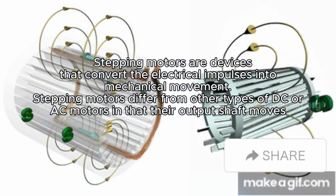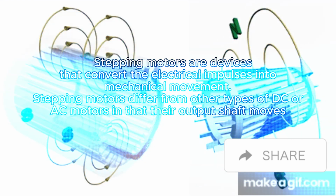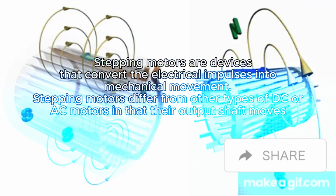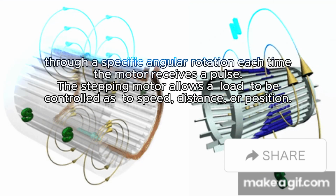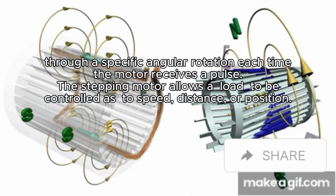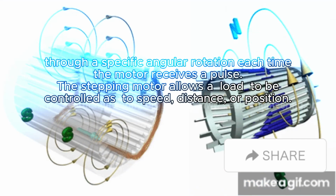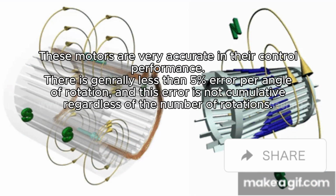Stepping motors are devices that convert electrical impulses into mechanical movement. Stepping motors differ from other types of DC motors in that their output shaft moves through a specific angular rotation each time the motor receives a pulse. The stepping motor allows a load to be controlled as to speed, distance, or position. These motors are very accurate in their control performance.